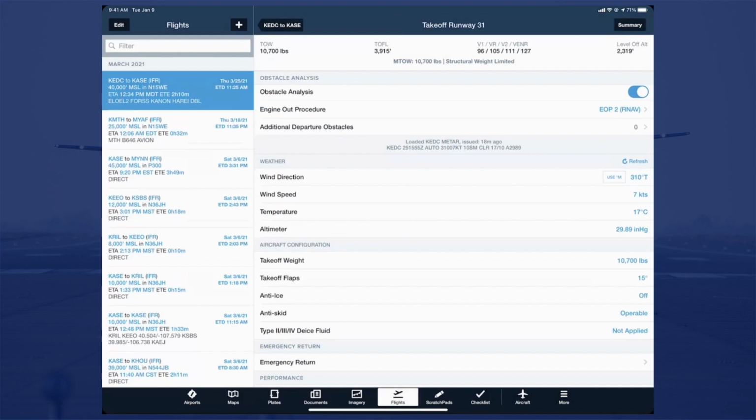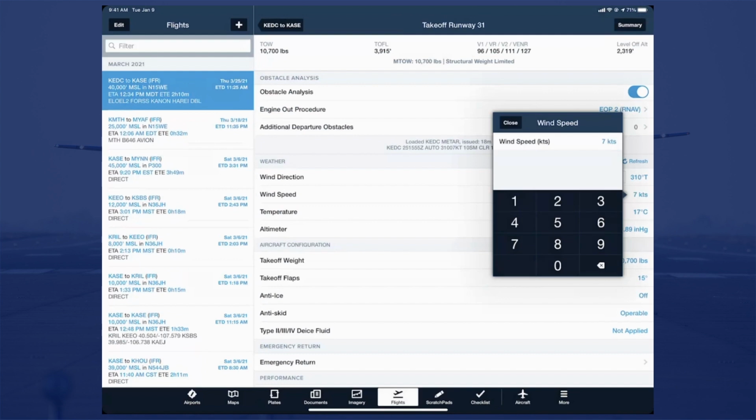And I've had to make those adjustments a number of times where, for example, there's a gusting tailwind going up 15 to 20 knots, but you get the static wind report and it's 9 knots, for example. So in that case, you would use that wind speed override as well.